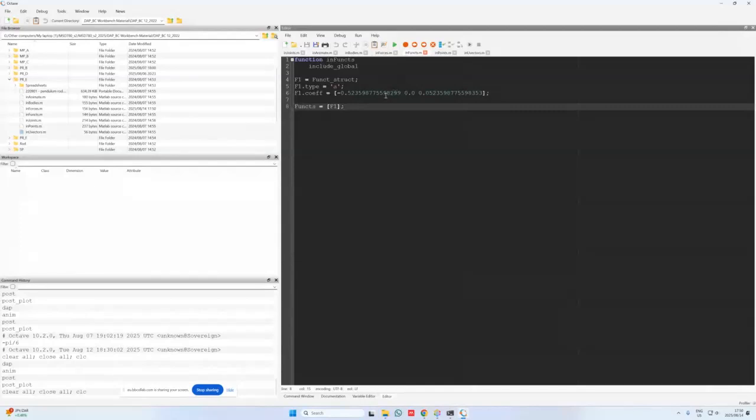If you integrate it twice, you'll get your position, your angular position as a function of time, and that will then be your driver constraint function that you specify over here. So it's a parabolic function, so therefore we simply specify the type of function as a type A function, and we give it the 3 coefficients as input in this case.